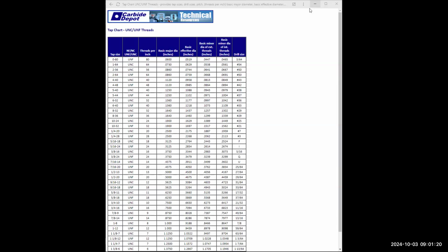If not, you can go back and watch this video. I'm going to click on this line, and I'm going to click on this grip, and I'm going to drag it over like this, right about right there. Click, enter. Okay. Now we got to trim this up. Go to trim. I'm going to click here, here, here, here, here, here, and here.